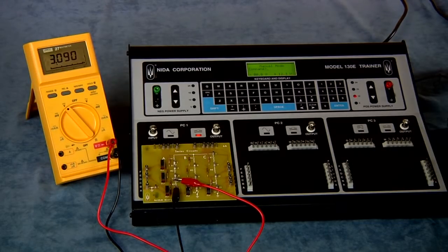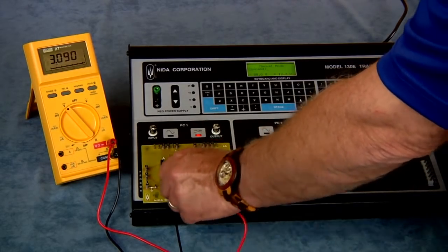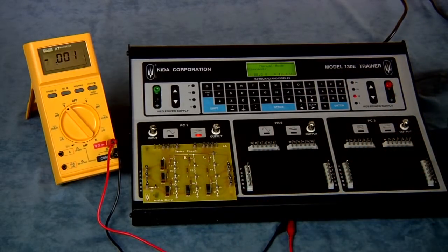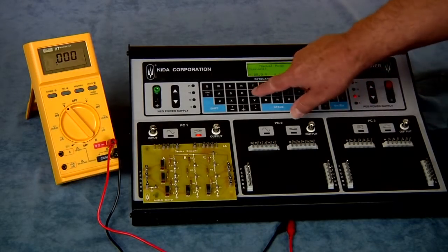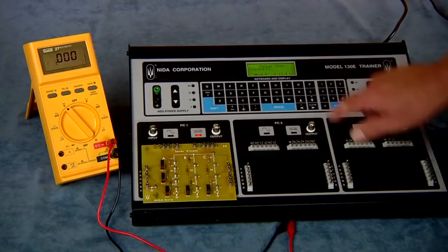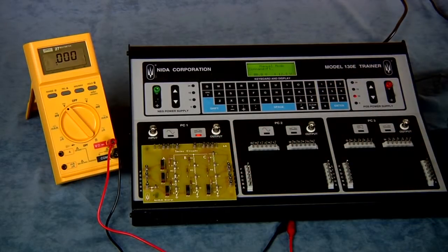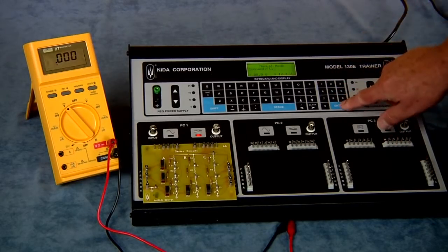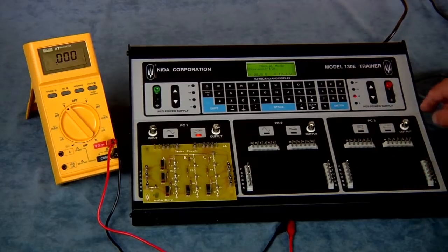Okay, so let's go ahead now and we're going to insert a trouble into this system. So I'm going to take the voltmeter off right now. And we'll enter in a fault. So we'll push the F, and we're in position PC1. So I'll push the 1 for indicating that it's that particular module that we're going to be working with. And the trouble I'm going to insert is going to be an open. And the one that I'm inserting is 10. So I'll just push 1, 0 for that, and then press the enter key.